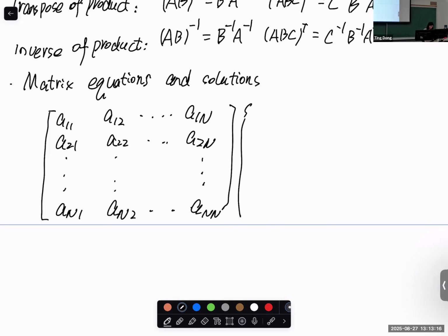So let's say we have a vector of things we need to solve, or in FEA, the degrees of freedom: displacement or rotation or anything. x1, x2, up to xn, equal to another vector, which in FEA could be the force in general terms, so force in 3 dimensions and the moment about 3 dimensions.